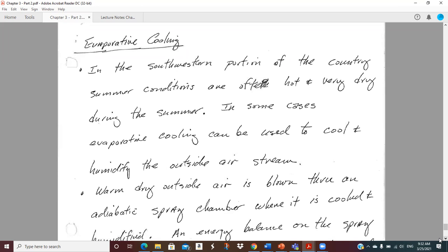In the southwestern part of the U.S. primarily, and other areas you might see this, typically areas that are pretty dry, we can create air conditioning by evaporative cooling, which means that all we need is a water source, a little pump, and a fan, and an enclosure, and some sort of a cheesecloth or some sort of a membrane that we can keep wet, pass air through so that the water evaporates.